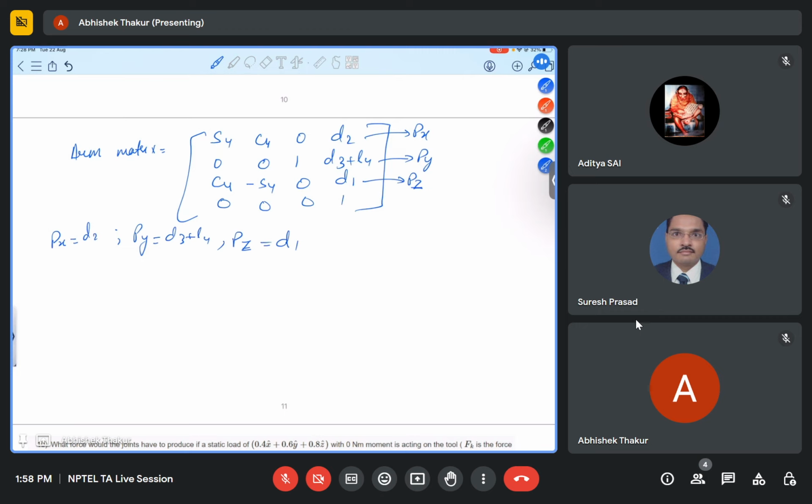So now we'll find the Jacobian. The Jacobian is given as AQ and BQ. AQ is associated with the linear tool displacement and BQ is associated with the angular tool displacement. Here AKJ Q will be the del of the position vector. So first we will find AK now.